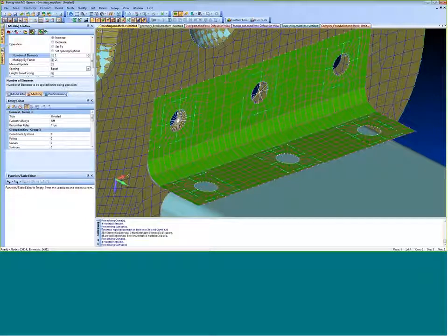And in fact, there's a message shown right here in your message window: potential rigid disconnect at element X and curve Y. Basically what it's trying to say is we didn't update the RVE because you originally didn't have that RVE connecting to every single node along that curve. And so they're just giving you a little heads up that if this is what you want, great. If not, you're going to work on this RVE. And so you can see if I go all around the sides, the RVE stays the same.